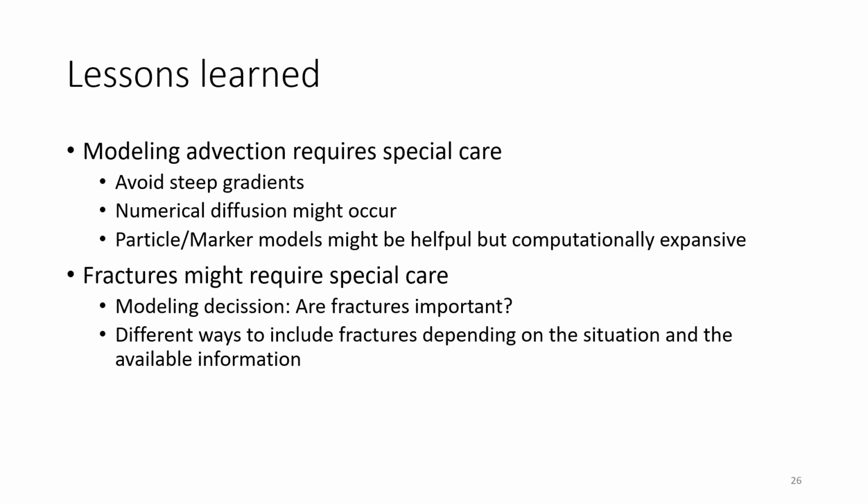And remember those possibilities I just explained to you. Do you want to go for a dual domain approach? Do you want to have a discrete fracture model? Maybe an embedded discrete fracture model would be the intermediate solution. These are really decisions you have to make early on in your model development approach. So when you go for groundwater flow modeling, an important question to ask yourself, to ask your client, okay, what about fractures? What size are they? What do we know about it? How important are they for the hydraulic processes we want to study? Thank you very much.